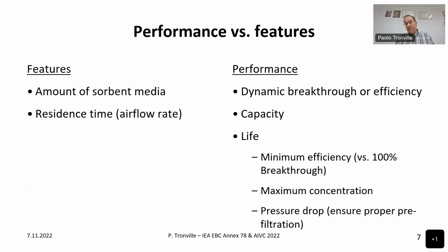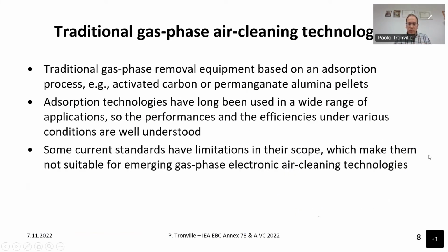Or even if the filter itself does not increase its pressure drop, maybe the pressure drop increases because there is a pre-filter, or it is not correctly pre-filtered, and therefore the particles that are always present in the air will finally deposit onto it. So it's not always easy to understand that.